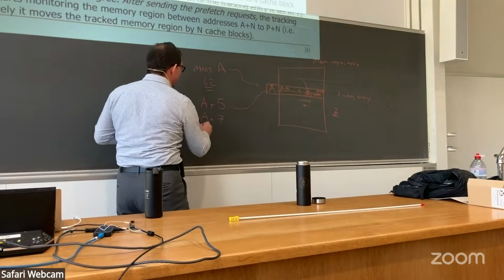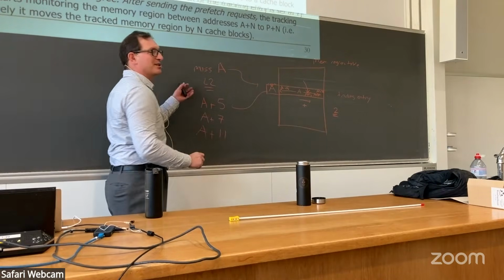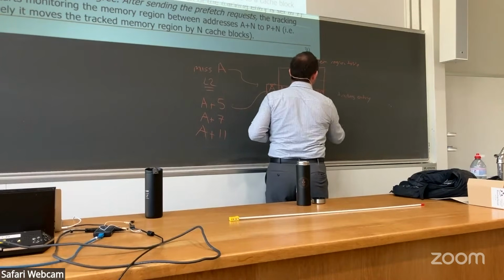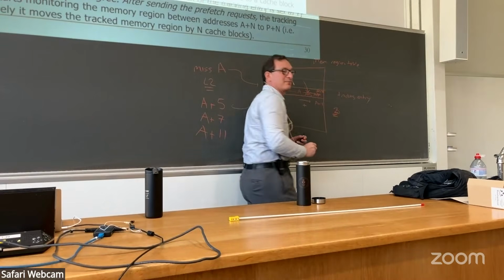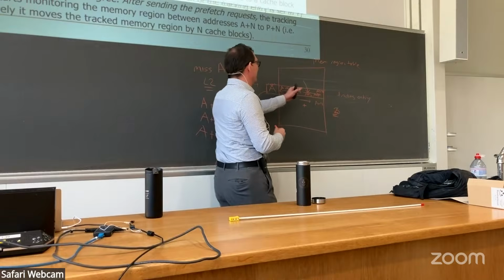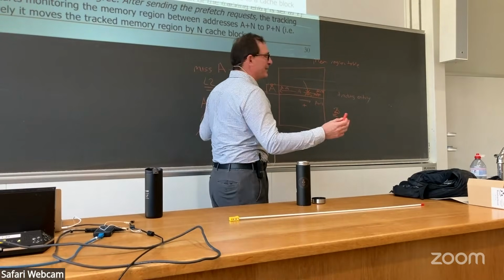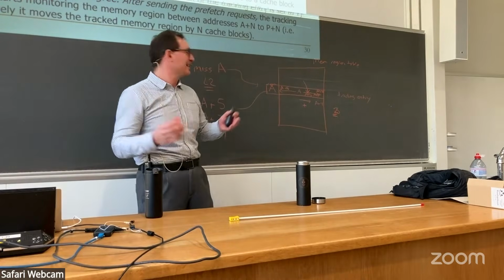And then the processor accesses, let's say, A plus 11. There's no regular stride still, right? Now you're really confident that the processor is going somewhere this way. But there's no regular stride, and confidence level is 3, because you've seen 3 accesses that are after A on a plus side, and there's no regular stride. And you want to capture this, right? And you have resources, let's say.